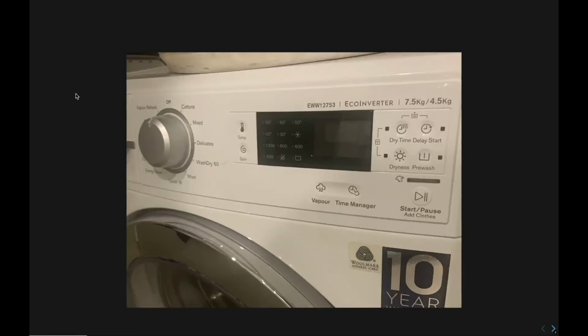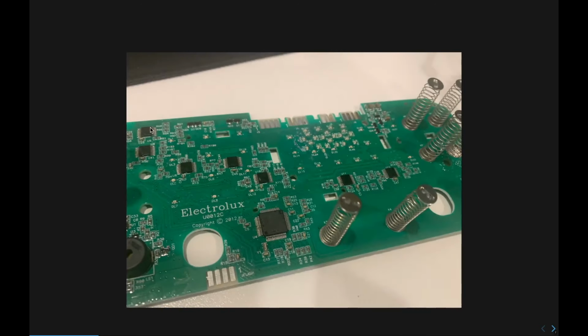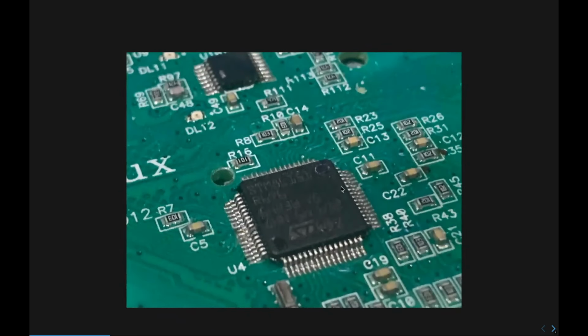So here's another example that literally hits home. This is my current washing machine. And of course, I opened it up for this presentation. Let's have a look inside. Yep, this is the board, and then these springy things are touch capacitive buttons, and those discrete LEDs are what you can see in the panel: times, programs, and different presets. Those connect to different boards, etc., etc. So, who is running the whole show? Of course, an STM8 microcontroller. So you see where the rabbit hole goes.